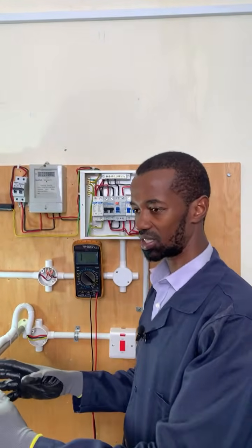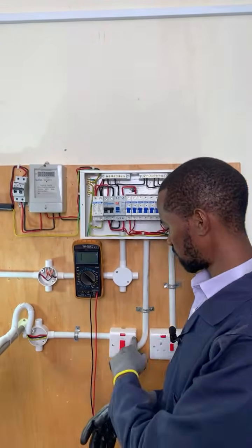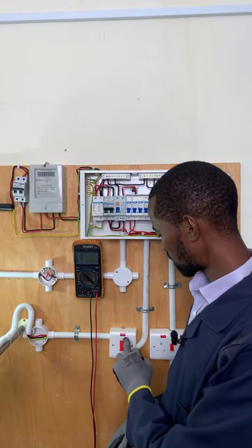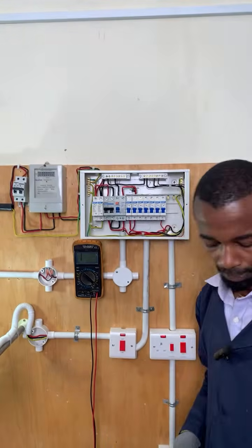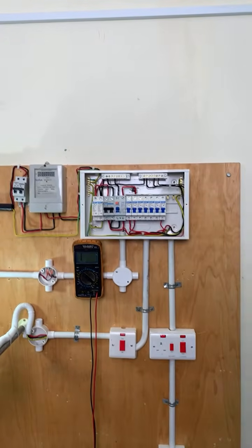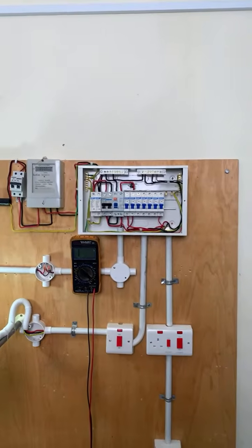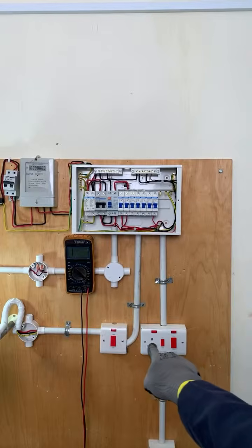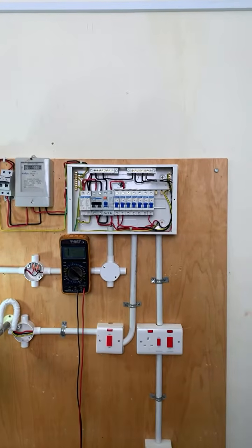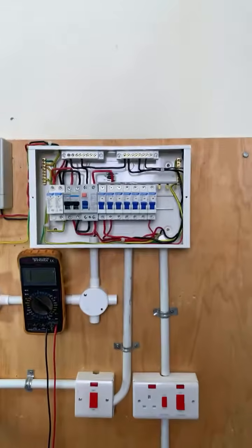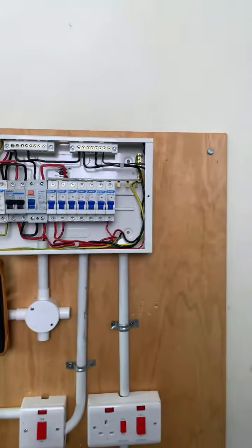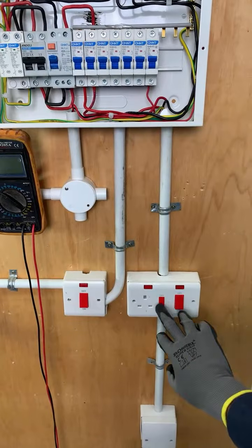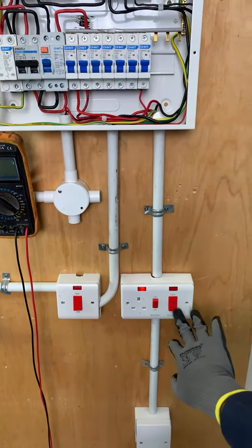If it is an instant shower head like this one, which is not working, it means that either the socket has an issue, and especially if the socket light is not turning on. For instance, these heating circuits, you will discover that they have those LEDs. If the LEDs are not turning on when the switch is turned on, then that is a first indicator that that specific switch or socket has a problem.